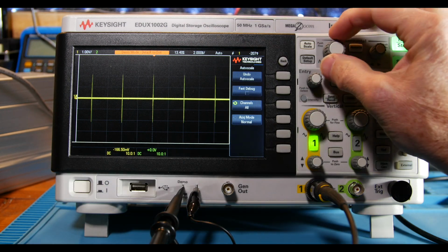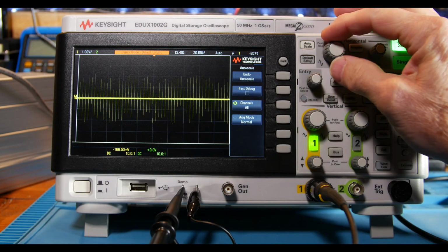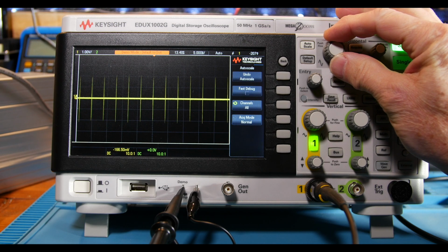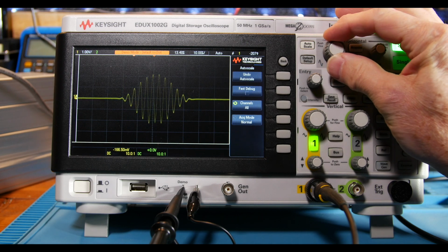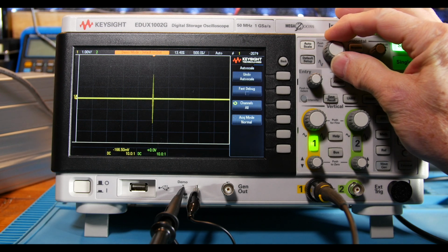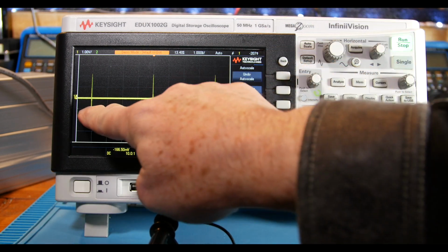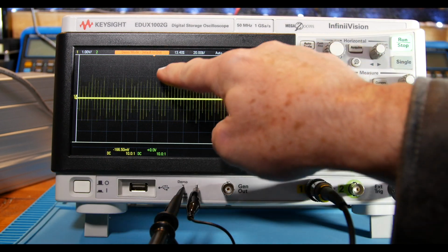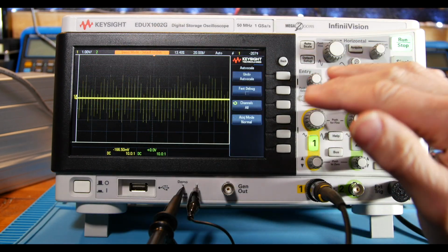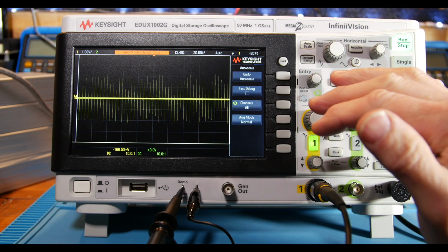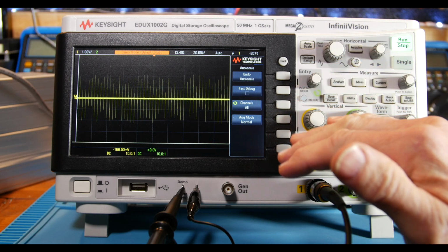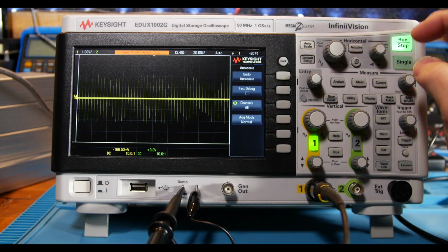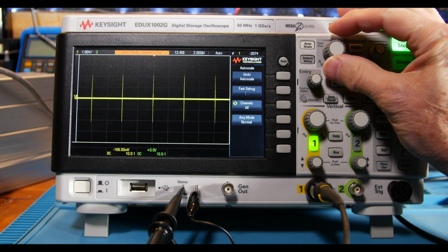So that's what you always want to do. You want to kind of look at the bird's eye view, like right there, and then you want to zoom in and see what's going on. So by the way, let's just do that. See, here's 3 of them. Now if I have too many of them, I just want to point something out. See how it's doing this? That's one of the things with the scope. It doesn't have a lot of deep memory. So when you get too many pulses, you're going to have some issues like that. There's some ways to get around that, but for now, let's just do this.